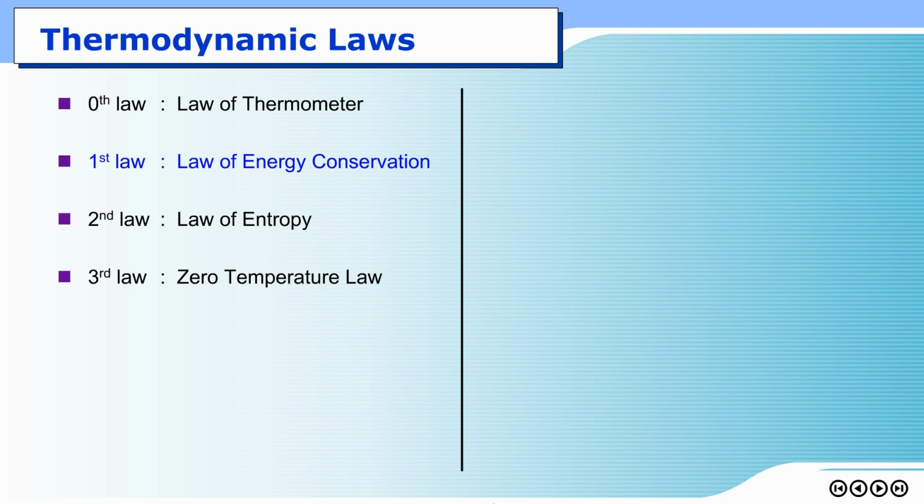For the first law of thermodynamics, we discussed in detail in lecture 2, both 2a and 2b. In short, we said that the energy is conserved. It can be transferred through the system boundaries in only two forms, heat and work. Within the system, the energy can be converted from one form to another, and there are three forms of energy: internal energy, kinetic energy, and potential energy.